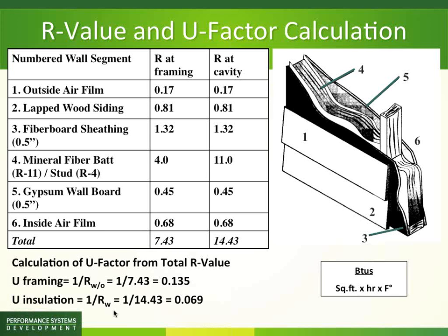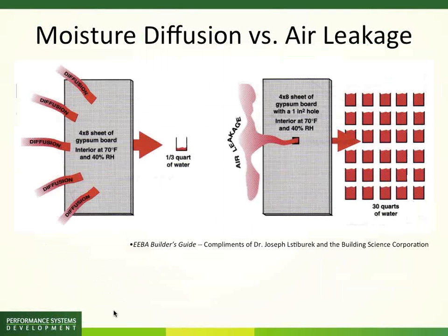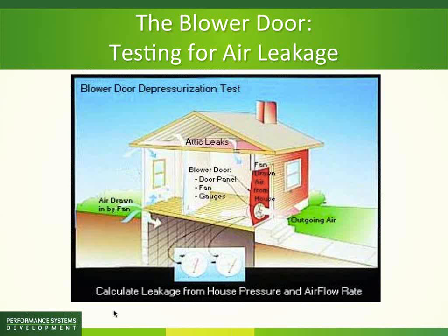So these are some slides of building science things that we wanted to show. There are way too many to show, but we did want people to see some of the stuff that gets covered during the course of training for building science purposes. You run into some of these things, like that moisture diffusion is what codes are written about, but the action is all in air leakage for the most part. Some stuff that's very eye-opening. Certainly was eye-opening to me when I got to it. Learning how to do blower door testing. We've already talked about that. How do you calculate conditioned floor area?